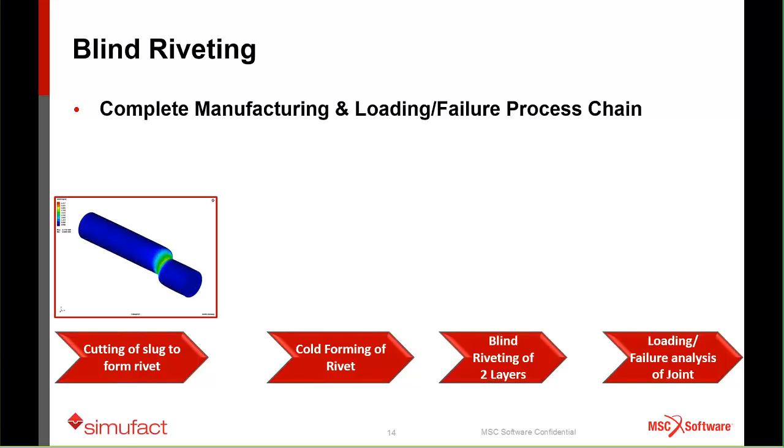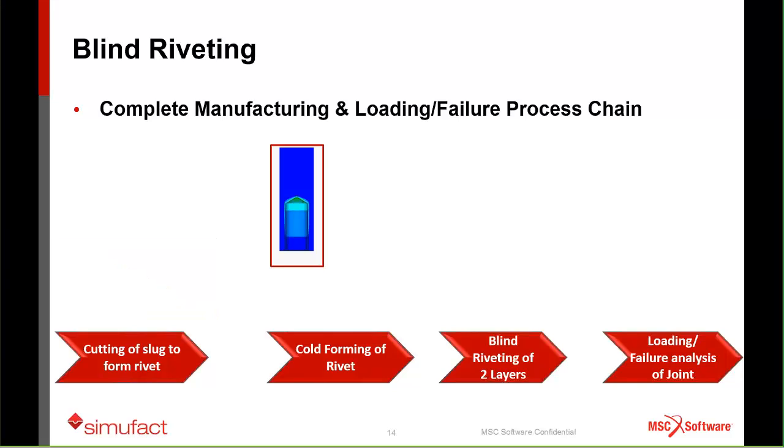So this is the first step. You have a wire of metal, and we simulate the cutting of the slug. That's the part at the end, which is then used to make the rivet. It's important to simulate this if you want a very detailed analysis, because as you see in the cross section, you get a buildup of stresses, and the shapes are different. There's some roll-off at the top, and a little burr formed at the bottom of the cutting process.